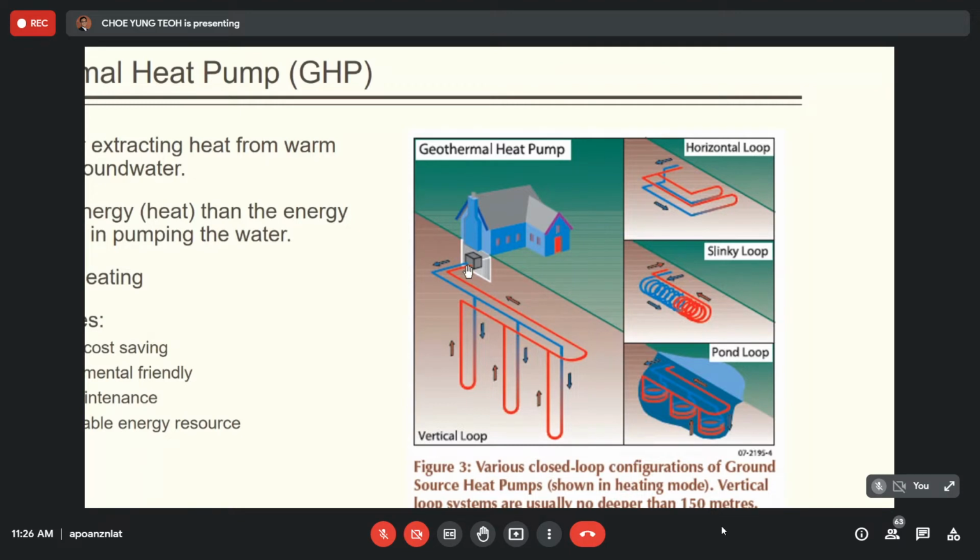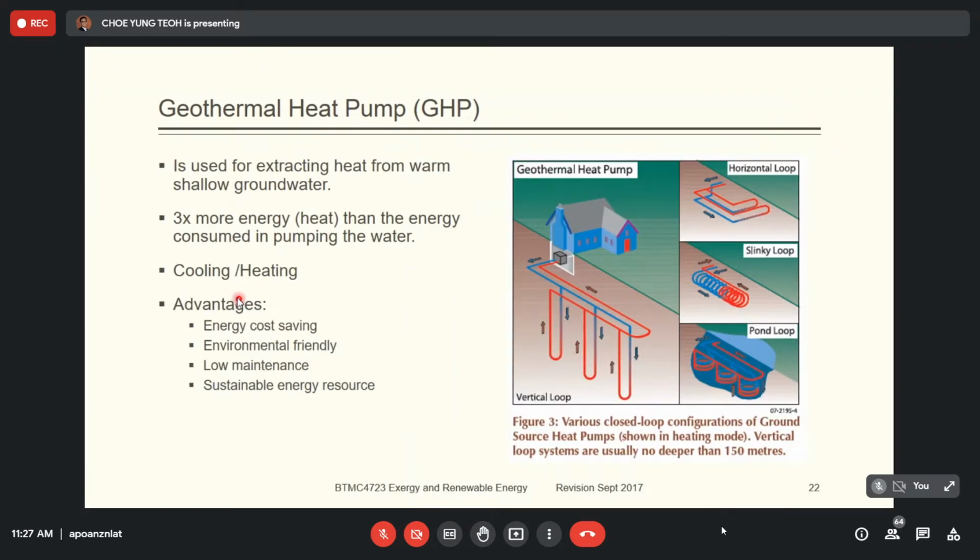So you have to arrange the pipe so that it's long enough to reach thermodynamic equilibrium with the underground water. This has to be studied to check the temperature of the water you pump in, the temperature of the surroundings, and how fast the heat transfer rate is, and then you can design how long the pipe is needed. But of course the concept is just to reach thermodynamic equilibrium. It means that the water inside the pipe and the water underground reach the same temperature. The idea is simple, so you can do it for cooling and heating, depending on what kind of resources.